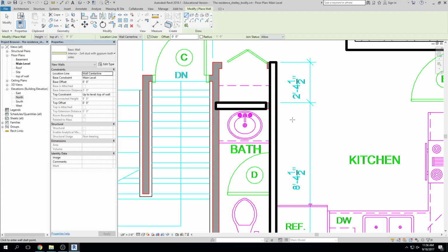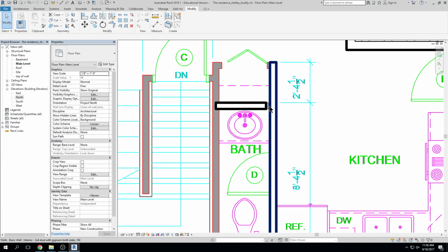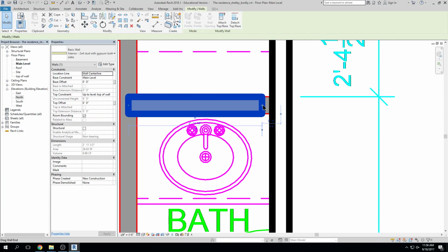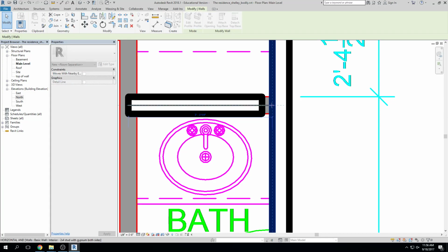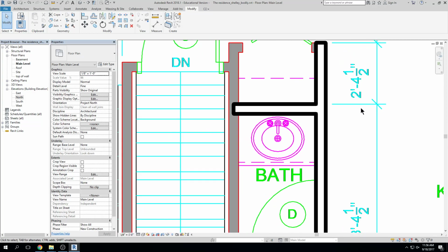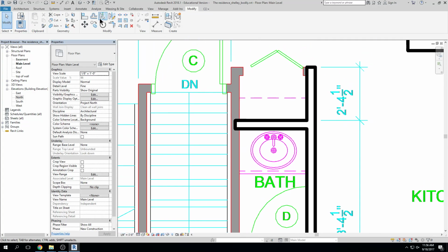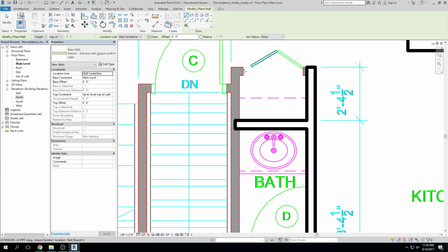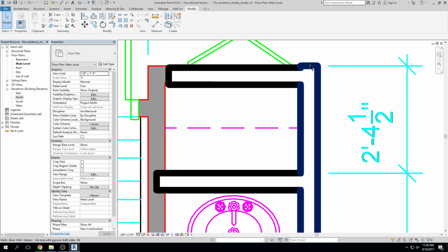One nice thing about Revit is that the walls join pretty easily, meaning if I don't quite touch those two together, I can come back in and click on one, click on that little blue grip, hold my mouse and drag it over, and it will join it and trim it, right? So if I don't get things quite where they need to be, it's very easy to fix it, essentially. Right, so there we go. Ooh, it didn't quite line up there, did it?